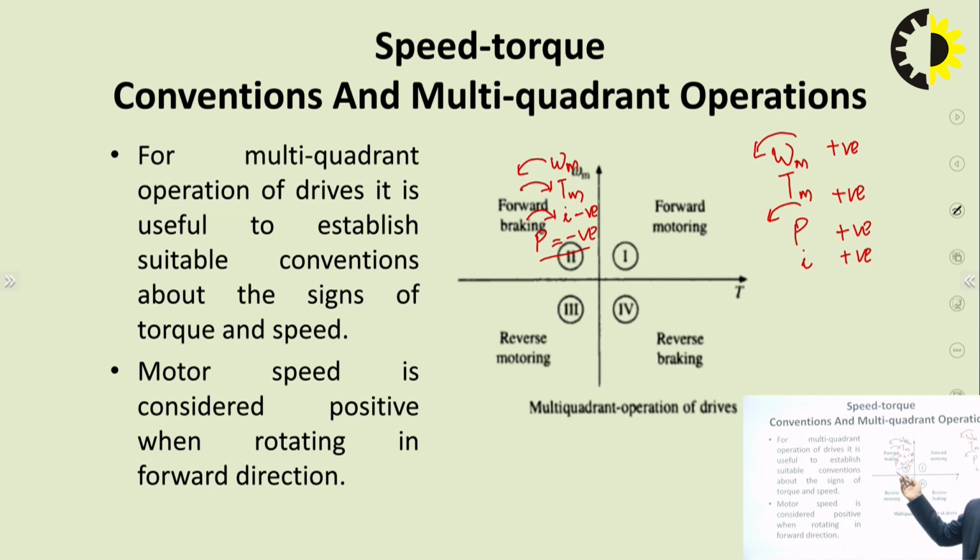And this is the fundamental which is used in electric vehicles also, and in the applications where this condition occurs, we can say this is the regenerative braking. So whenever we can make the arrangement so that power flow can take place from load to the source, that will make the condition of regenerative braking.